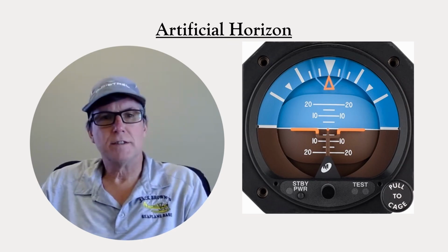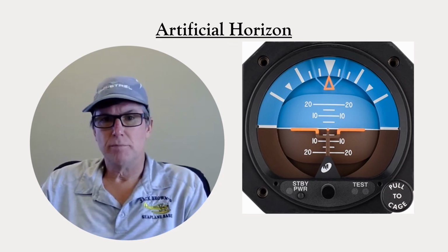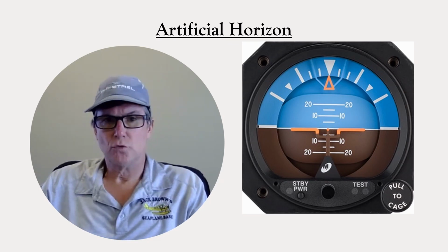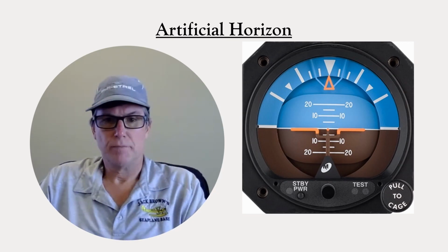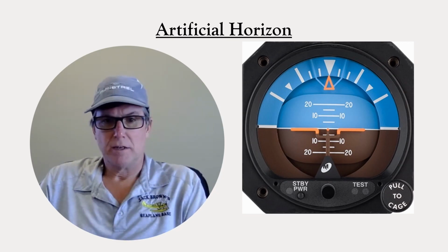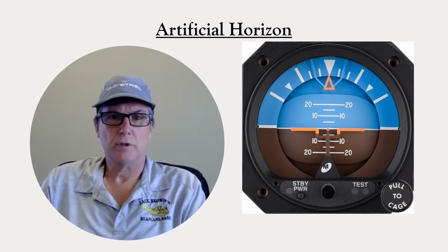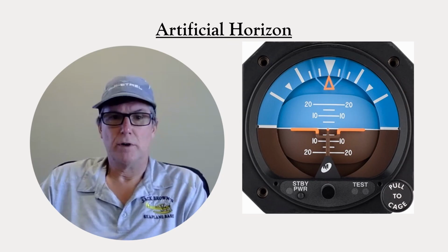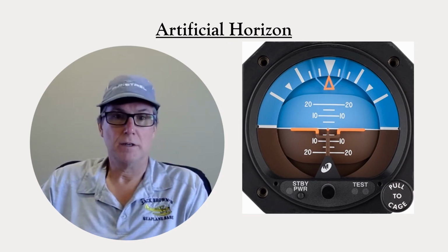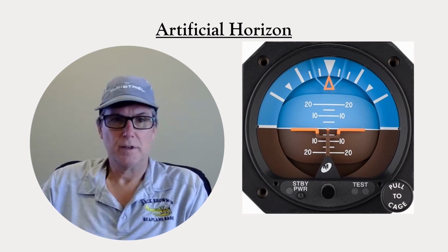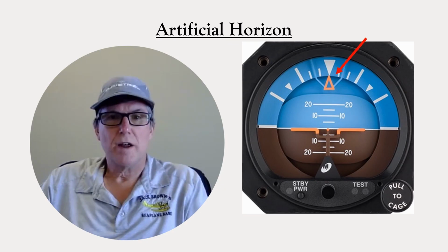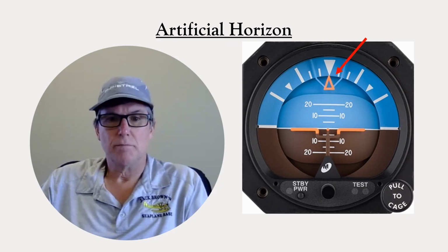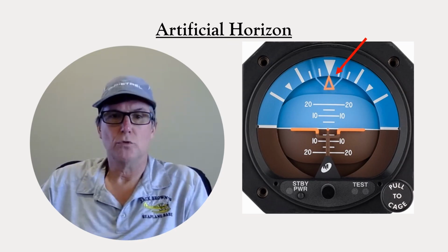On your artificial horizon, the orange parts stay in position relative to the instruments, and the blue and brown parts stay in position relative to the horizon while the aircraft moves around the instrument. I'm referring to these parts by color with respect to the illustrated example here. The corresponding parts on the artificial horizon in your airplane may be different colors than this. The bank angle is indicated by where this orange triangle is relative to the tick marks on the perimeter of this blue ring.